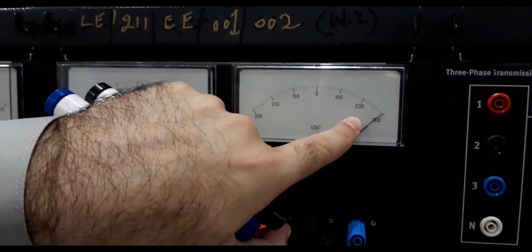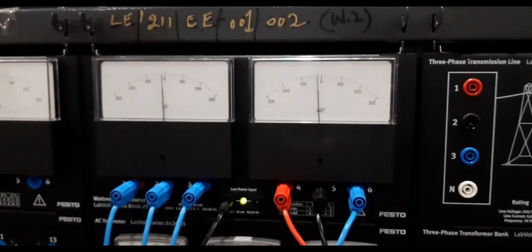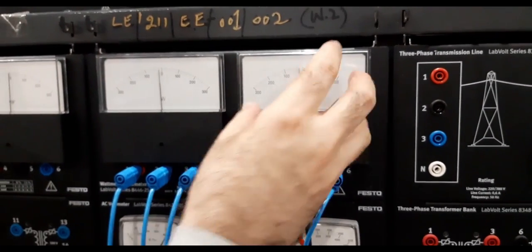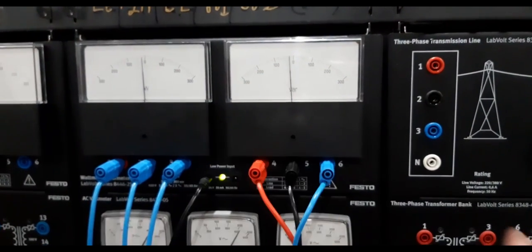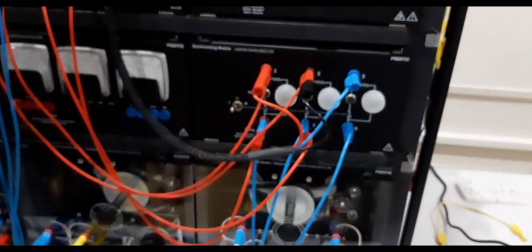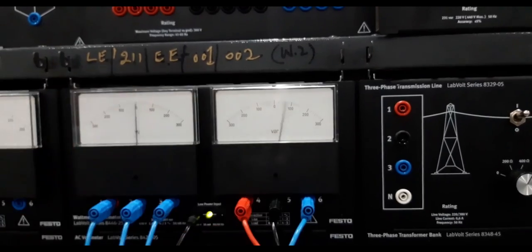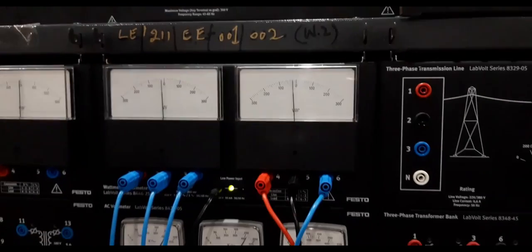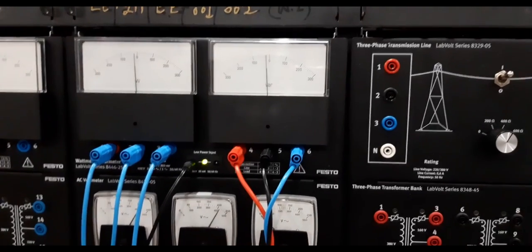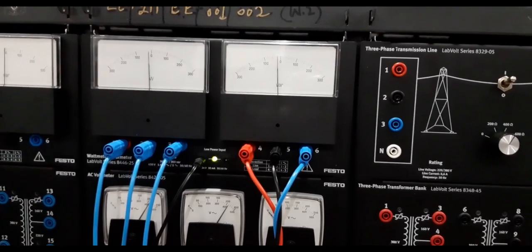You see, it has now become a large consumer of reactive power, and that is basically the case when we have induction machines. So induction machines or induction motors consume a large amount of reactive power, as I have demonstrated: this machine is connected to the system, and if I turn off the excitation, let me do it again. If I turn off the excitation, it consumes a large amount of reactive power, and that is basically the indication that it is an induction motor. Because later on I will talk about the induction motor, so I was thinking to give you even a sort of demonstration about that.